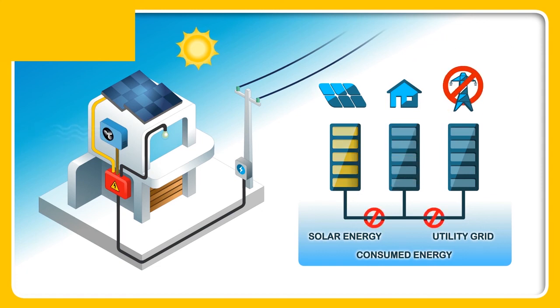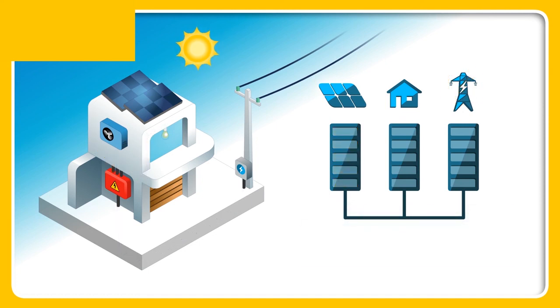When the utility grid fails, grid tie systems will not operate, not even on solar power. This allows utility employees to fix the power line safely without worrying about solar energy systems that are still feeding electricity into the power lines. In areas with frequent power cuts, an additional battery backup system is advisable to supply energy in case of grid failure.